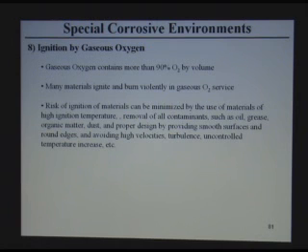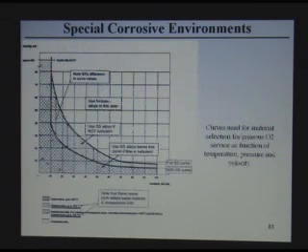There are charts that help with material selection, and this is one I picked from one of our customers. It is a function of the pressure of the system and the velocity. In this zone, you can use carbon steel with stainless steel trim. In this area, you have to use stainless steel. And above that, you have to use nickel alloy.